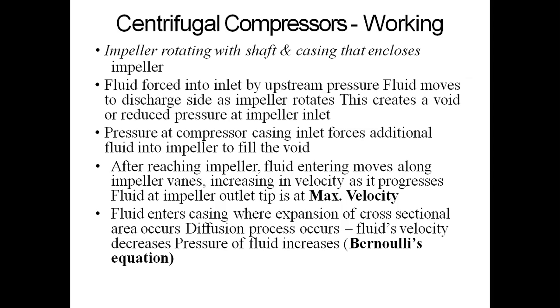The fluid enters the casing where expansion of cross-sectional area occurs and the diffusion process takes place. Fluid velocity decreases and the pressure of the fluid increases.